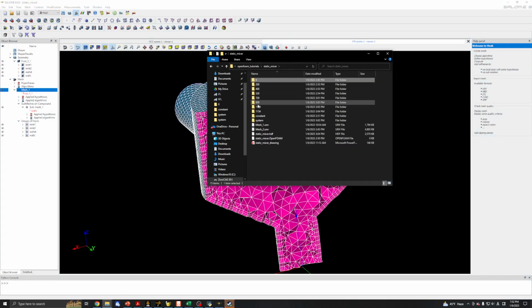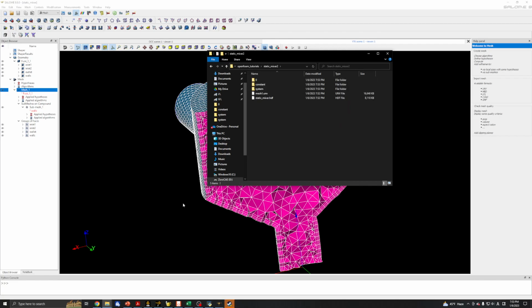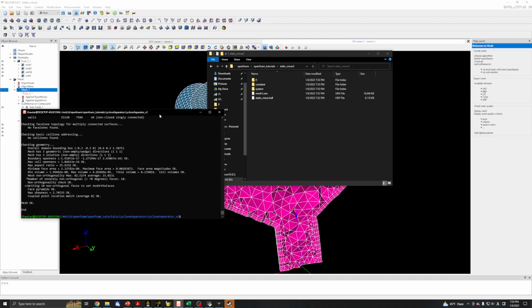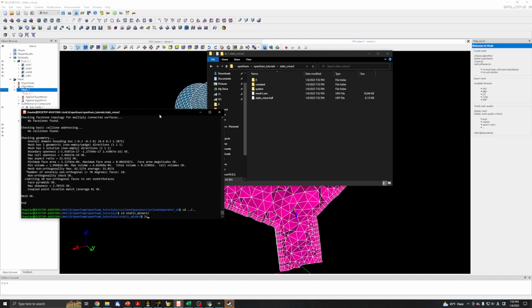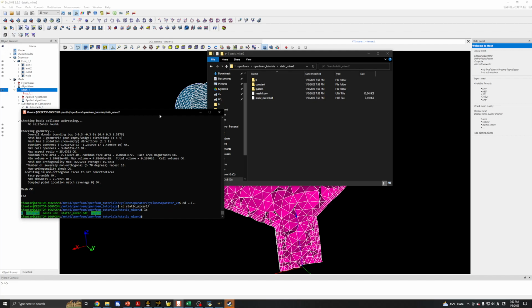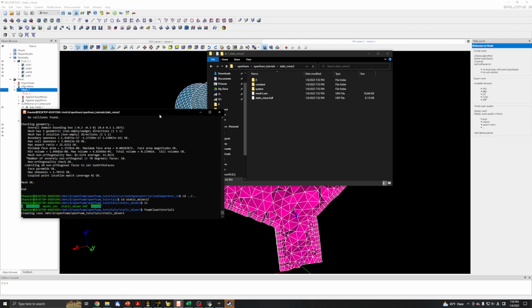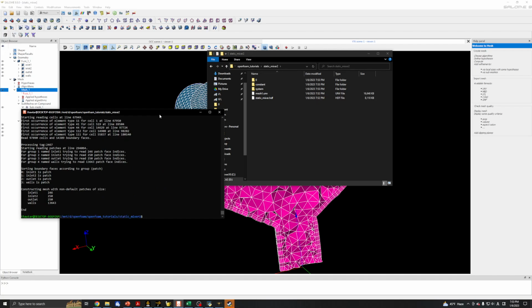So I prepared the required OpenFOAM files, so we can start creating a mesh. Static mixer 2. Okay. Now we clear up, and okay, so the command is ideasUnvToFoam, and the input is the mesh file mesh1.unv, and OpenFOAM will convert the mesh, so we can check the mesh.